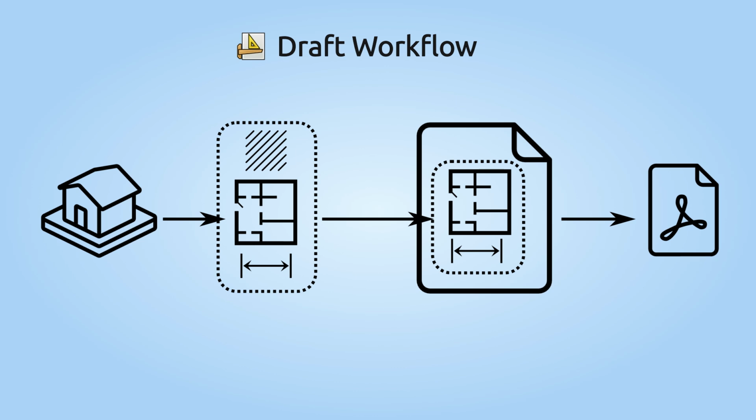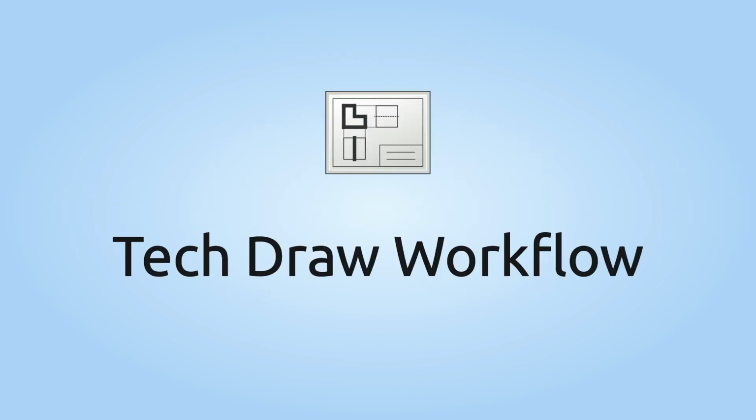The disadvantage is the creation of 2D objects, such as plan views or sections, as an additional step in the 3D space before placing them on sheets. Even though these 2D objects change according to the changes in the 3D model, they don't maintain all the parametric data of the 3D objects, and things such as dimensions may need to be adjusted manually after the changes in the 3D model.